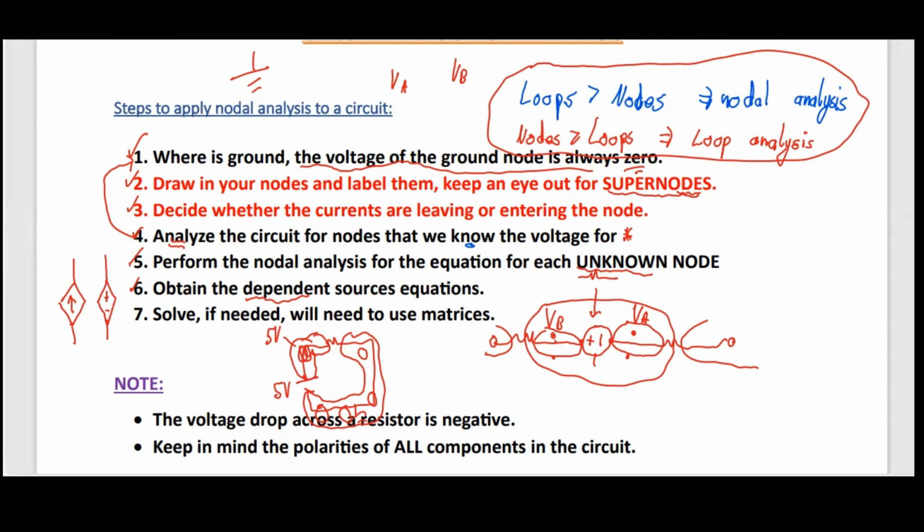All these things do is provide a constant voltage or current, and these voltages or currents depend on somewhere else in the circuit. It might depend on some voltage drop across a certain resistor somewhere else in the circuit, or on some current somewhere else. It's dependent on something, and that's why they call them dependent sources.